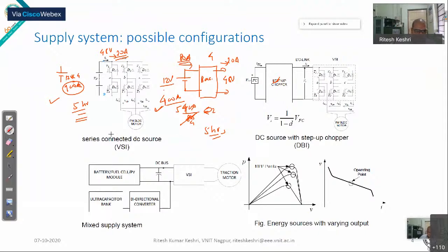The issue is that there's a linear relationship between the Ah and the weight of the battery. To double the Ah, the weight will be double; 4 times, 4 times. So you don't find any benefit in the power to weight ratio. Unnecessarily you are increasing the control components. So that's why you don't see people use this